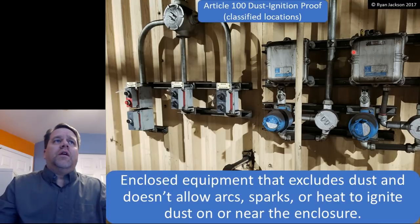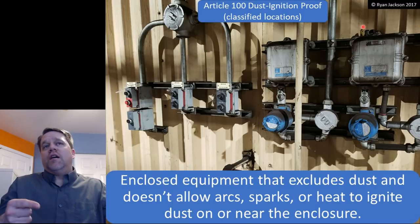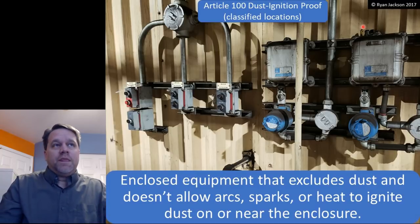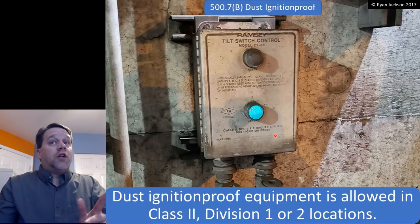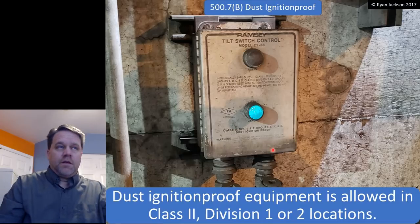If we go to Article 100, it's enclosed equipment that excludes dust and doesn't allow arcs, sparks or heat to ignite dust that's on or near the enclosure. Very similar to explosion-proof. And to be perfectly honest, usually, dust ignition-proof is also explosion-proof. Usually, not always. This one is just dust ignition-proof.